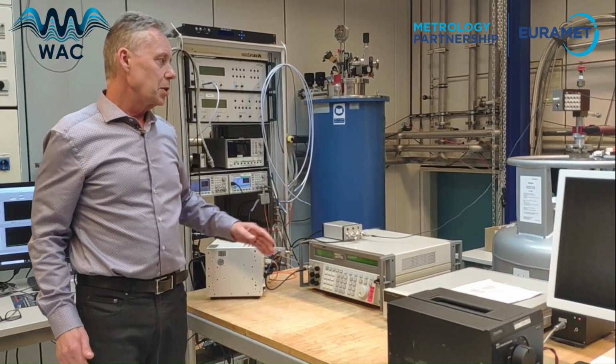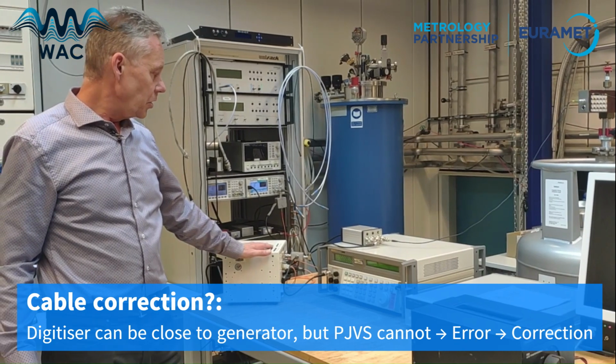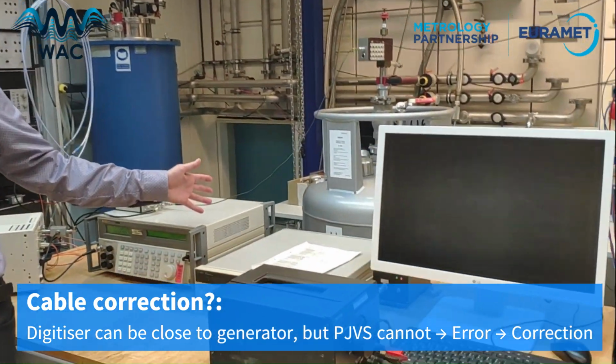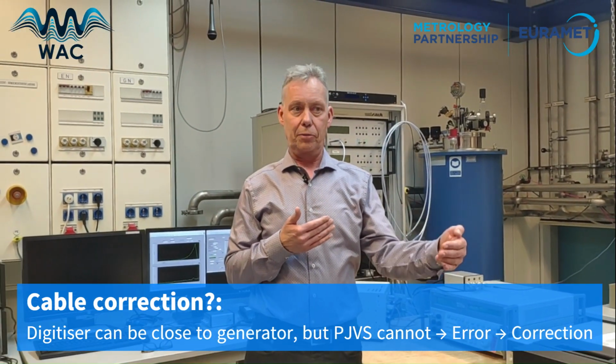For the cable correction, we have to consider that we can bring the digitizer very close to the generator, but the Josephson array will always be down in the liquid helium, so far away from these two instruments. And this long cable makes an error which we have to correct for.